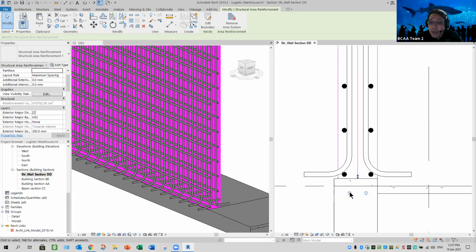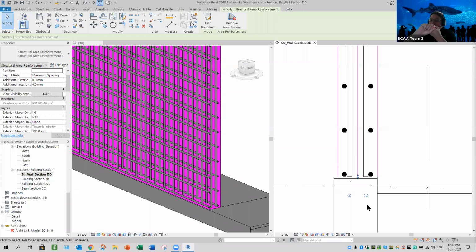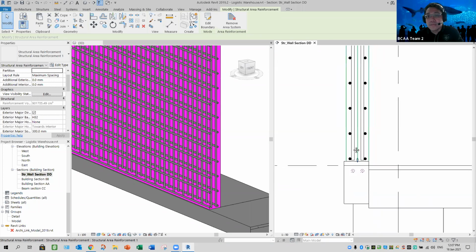See the structure? All this can be toggled because you need to tie to somewhere. If not, this wall is useless. It will also collapse. Correct? That's why you can see precast walls, they have rebar or the reinforcement system with some extension so that they can tie to surrounding joints, your column, your beam, and so on.